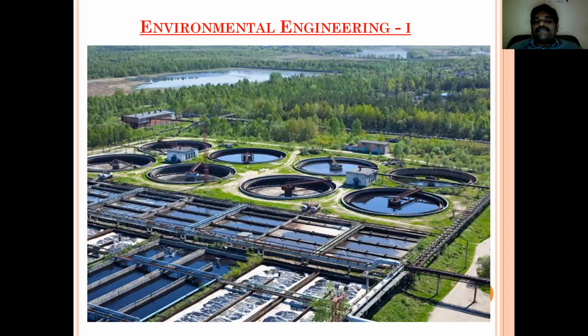After plain sedimentation, the next step is sedimentation with coagulation, right? After coagulation, the next step will be filtration, softening, disinfection, distribution. All are constructed one by one in a sequential order, which we discuss as a specification to construct a treatment plant. Understand?